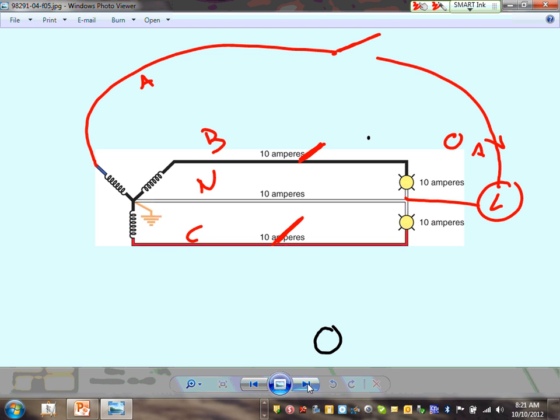Why do you think the NEC code book came with 2 things? Number 1, multi-wire branch circuits have to be tied together. With that came a disconnect for that fixture, exactly to solve this problem. Now, by code, this fixture above your head has to have a disconnect within sight.